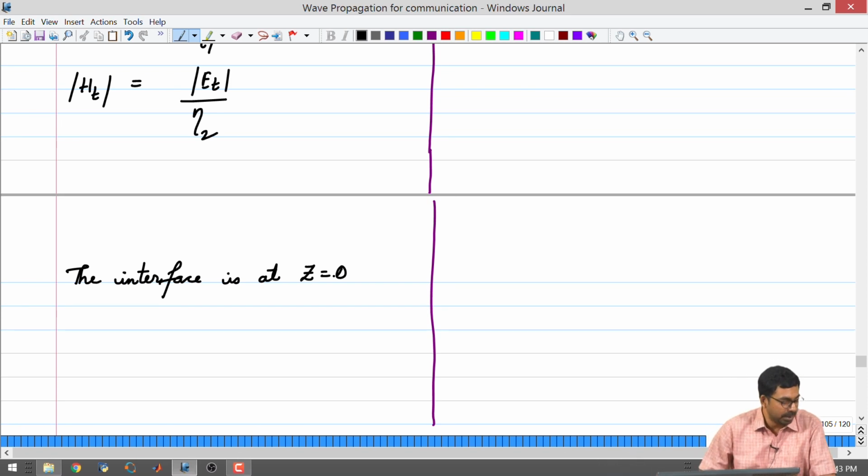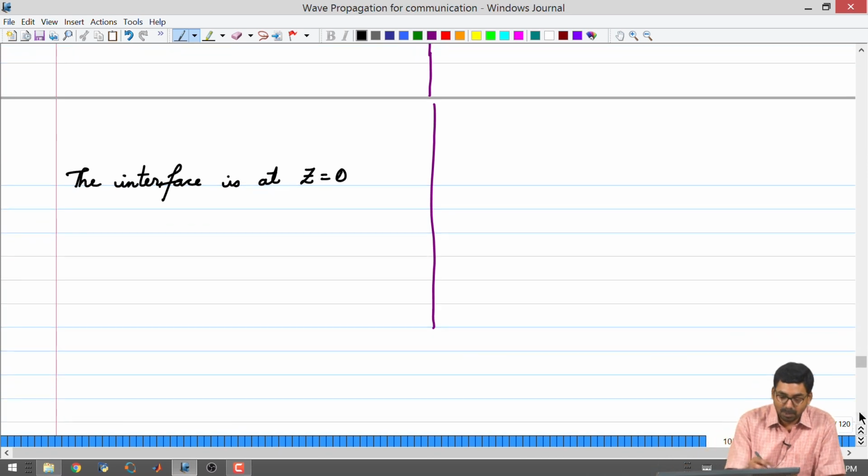Okay, the position coordinate with respect to z, when z equal to 0 marks the discontinuity between medium number 1 and medium number 2. So, at z equal to 0 is the exact interface, alright. So, at the interface we need to apply boundary conditions, and the boundary conditions for dielectric interfaces is tangential E fields are continuous, tangential H fields are also continuous, that is it, alright. So, now what we are going to do is we are going to apply these boundary conditions.